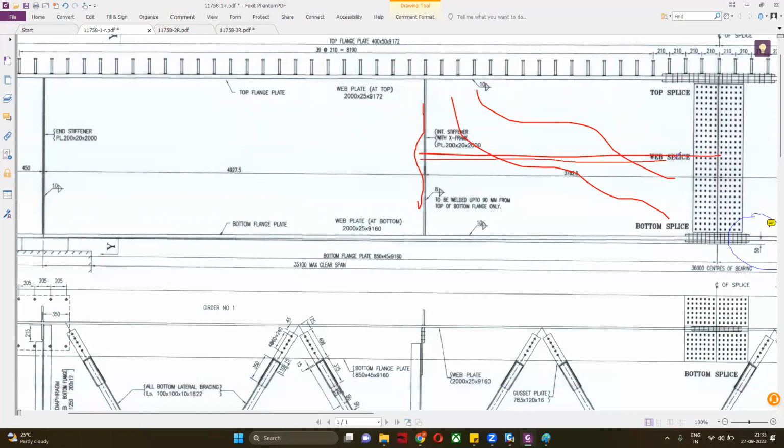Formulas have been given to predict this, but this is the general behavior. Is the plate buckling like this, sir? It will not buckle straight. Your plate will not always buckle straight; it generally buckles in a diagonal direction. So for resisting it, we need to provide this again.